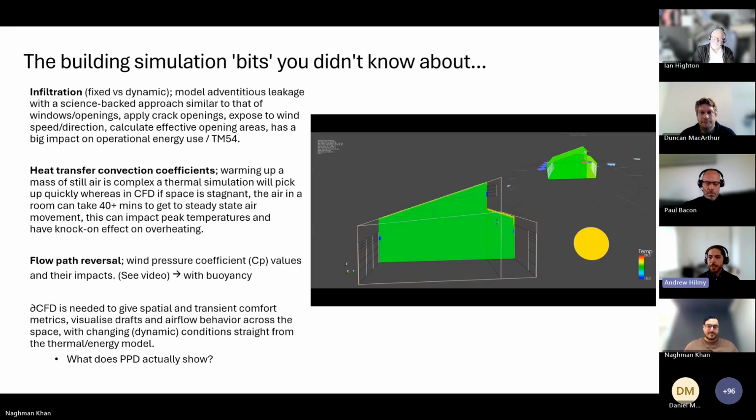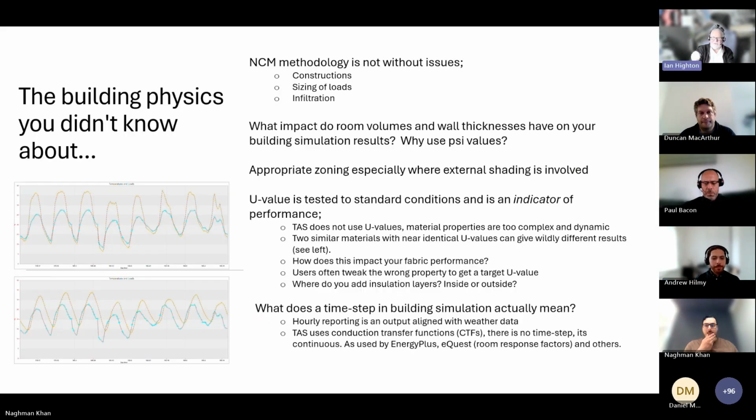There's also the ability to model wind-driven ventilation infiltration in the building simulator as well. There's an option in heating plant room controls in TBD where you can, there's something called infiltration coefficient. You can play with that, and that makes it wind-driven to a certain extent. So if you want more details on that, just contact us. It's not as good as having the absolute wind speed and wind direction, that it's going to be coming in from that side, but it does allow you to modulate infiltration based on wind speed. So at least that's a step up.